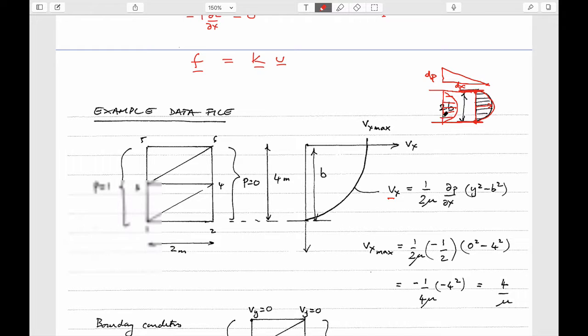So clearly, if it's steady state, it would look identical at this point here, at all times that you took a picture. If the velocity downstream is identically equal to the velocity upstream, then clearly as you're going from upstream to downstream, there's no convective acceleration. It's not going at one velocity here and a different one here, in which case it has to accelerate and work against inertia. There is no convective acceleration in the system. So the only loss in the system is due to viscosity.